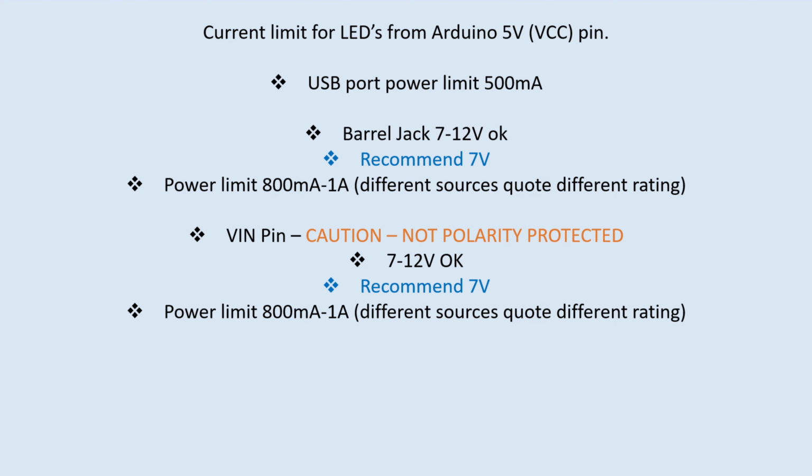Where this is neat is that the new motor driver from the DCC-EX team provides power to the Arduino board, and from the comments I have received from them, they thought about 2 amps of power. So it's plenty to drive this 800 milliamps available through the voltage regulator, because that's what you're actually going to end up with. It does offer more on the input from their board, but you can't do anything with it.